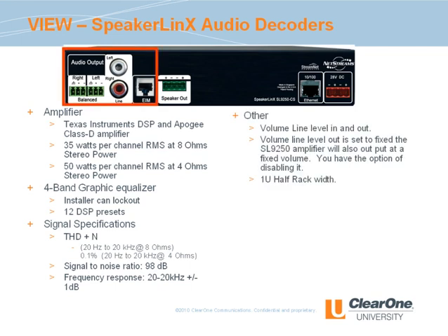The SL9250 supports an EIM connection. The EIM connection is used to attach accessories and provide a signal path for a local audio source or for connecting an external amplifier or powered subwoofer. Unique to the SL9250 are RCA and modular connectors specifically designed for balanced line level audio out.